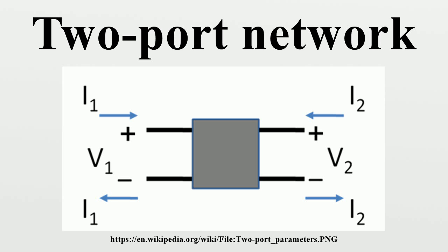This problem can be resolved by inserting an ideal transformer in the output port of at least one of the two-port networks. While this is a common textbook approach to presenting the theory of two-ports, the practicality of using transformers is a matter to be decided for each individual design.